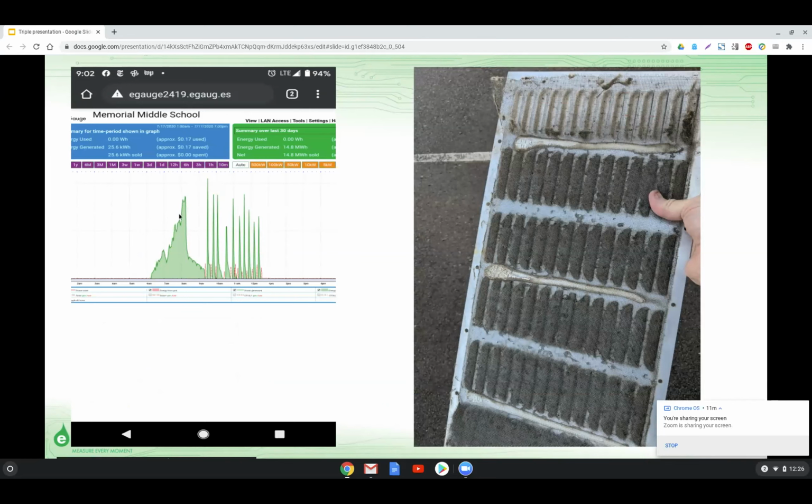More inverter failures here. Normally with inverters, if you only get 15-minute data, they're going to round off these inverter drops and shutdowns. Whereas the eGauge, because we can do second-by-second data, you can zoom into what's called the 10-minute view right here and look specifically at these drop-offs and see, okay, it looks like the inverter is capping, shutting off completely for 5 minutes, cycling, going back on, running for the same amount of time, and then shutting off again throughout the day.